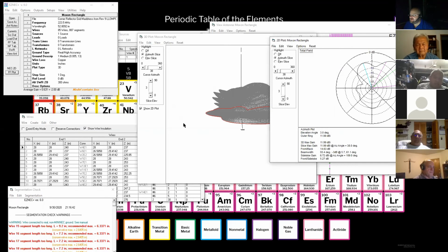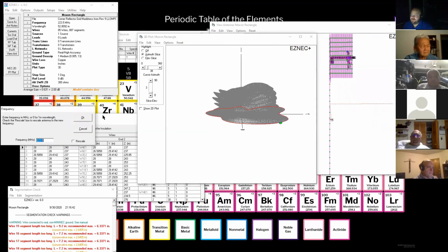And I was able to find the happy medium to be able to run 3 bands and get 3 usable patterns. And this is sort of a funky pattern, but it's got a great lobe forward, almost 12 dBi of gain forward. And the reason why it's offset side to side like this is because there's all sorts of different elements off of this antenna because it can work on multiple bands. But I found the distance that worked on the 3 bands that I wanted to use.